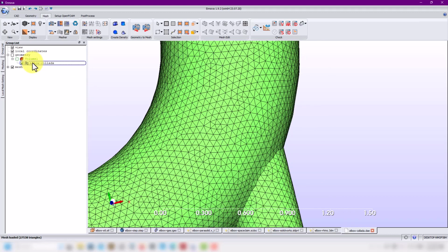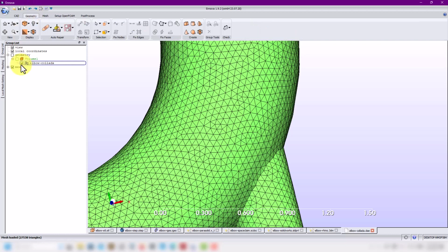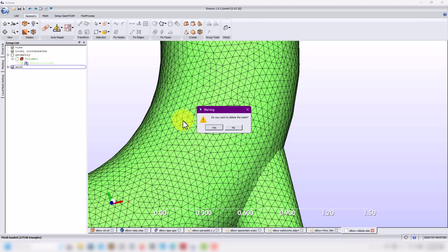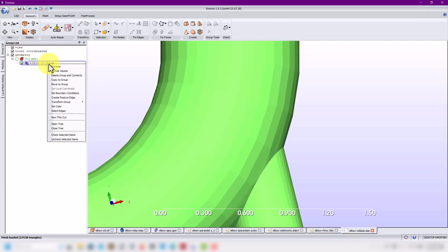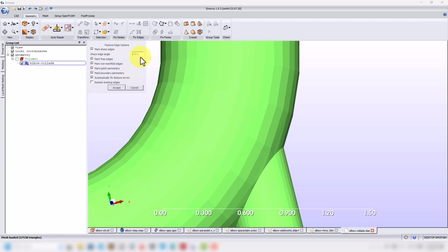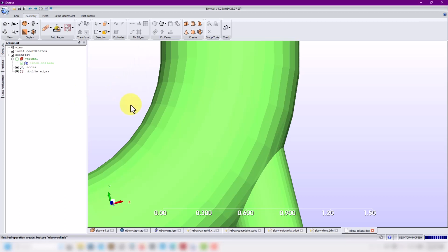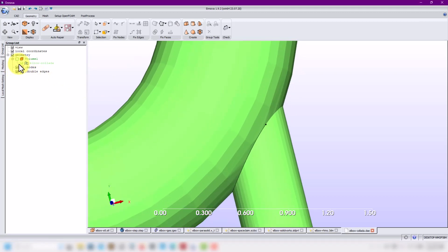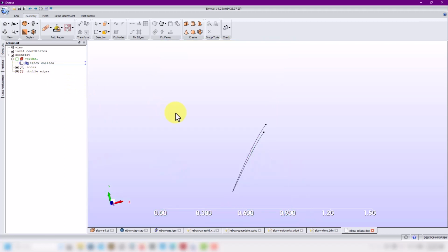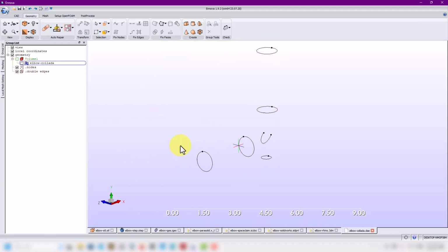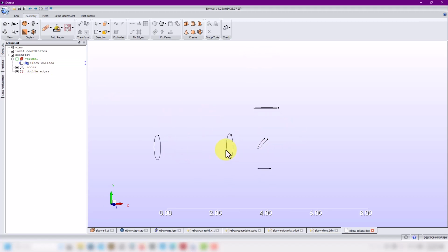So as you go here also, right click in your geometry, let me go geometry model, let me erase that mesh, delete mesh, and right click here and see that you have this create feature edge. Feature edges, same stuff that you have in part of your OpenFOAM. So you give an angle and so on, and see that now putting 45 here, and the same concept, the smaller, the more features you capture. See that you capture those features, and now that you have those features, it will be able to resolve, in particular here.